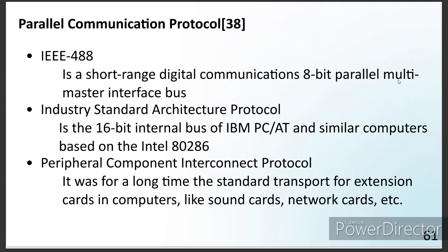When compared to the alternatives at the time of development, the IEEE 488 protocol was particularly well suited for instrument applications. IEEE 488 is essentially a bus on a cable with 8 parallel data transfer lines and 8 dedicated control lines. Given the demands of the time, its nominal 1 megabit per second maximum data transfer rate appeared adequate. Even today, the GPIB interface is powerful enough for many highly sophisticated and demanding applications.